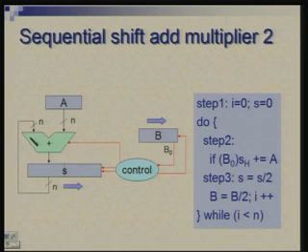And having done this, there is another interesting observation which can be made, is that we have now two registers S and B which are shifting right. So initially S has all zeros, and as you perform addition and shift right, the bits keep trickling into the right half of S. Initially everything is 0.